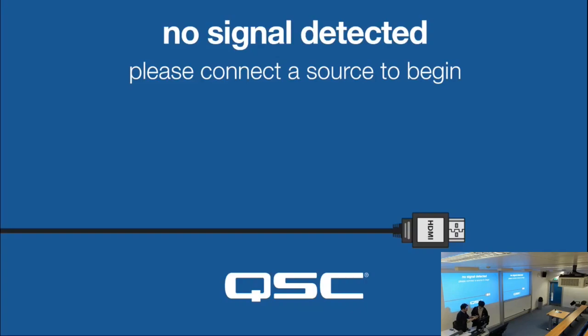Which means there's a controller to control this line buffer, and it knows what the row number is, and at the 4th clock cycle, it knows it's time to feed the outputs of the first line buffer to the next line buffer.